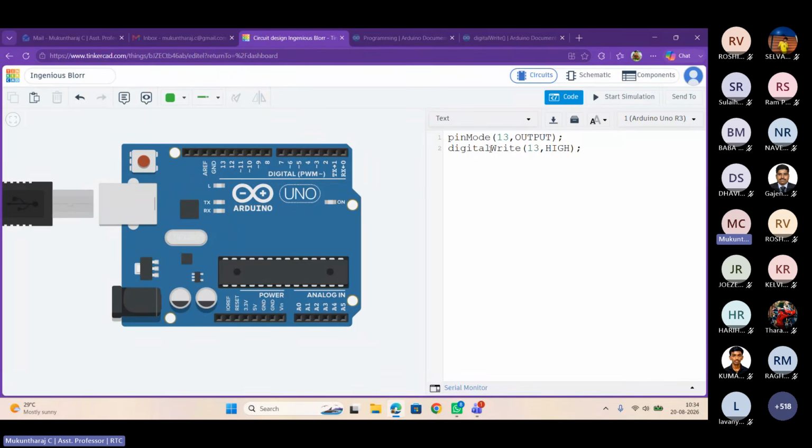Yes. So we are going to provide pin number 13 a logic high. That is what this function is going to convey. Digital write: the controller is going to write a value called high, which refers to 1 or 5 volt we can take. And I have told you one condition that to make the LED glow, we must provide the pin with the value high. That will be under one condition, how the LED is being connected with the pin. We will discuss that while you connect with the external LED.